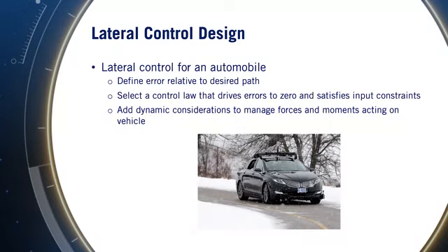Control commands must be cognizant of the available tire forces and not exceed the capabilities of the vehicle when correcting for tracking errors. The reference path is a fundamental interface between the planning system and the lateral controller and can be defined in multiple ways.